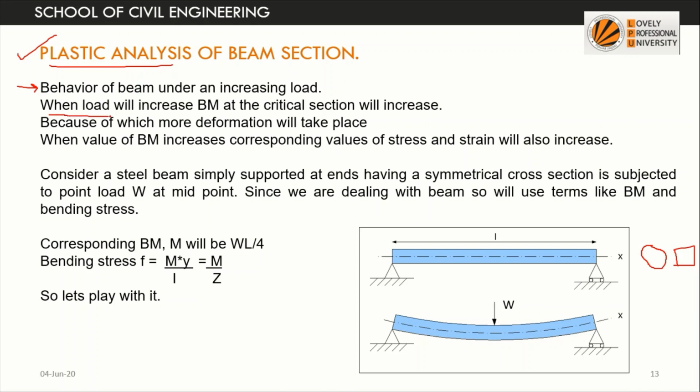We know that when the load is increased, bending moment will also increase. With an increase in bending moment, more deformation takes place. Deformation corresponds to strain, so the value of strain will increase. So when the bending moment increases, it will lead to an increase in the corresponding values of stress and strain. This basic background we should always remember. First, when a load is applied, there will be bending moment. When a bending moment acts, there will be some deformation. Because of deformation, there will be stress and strain.